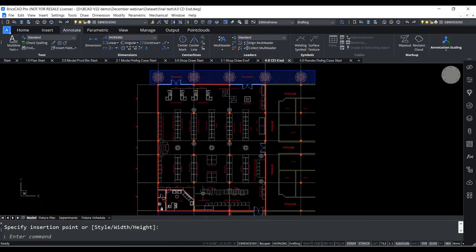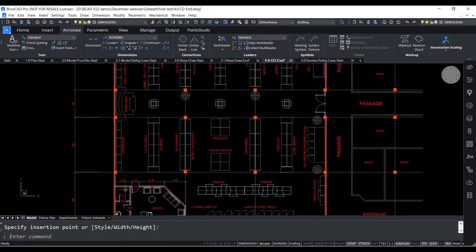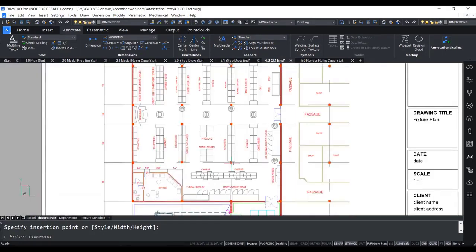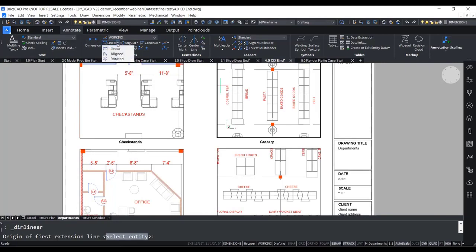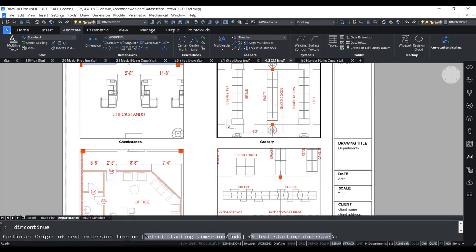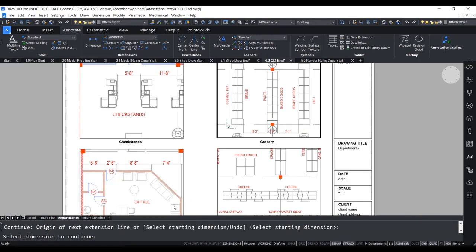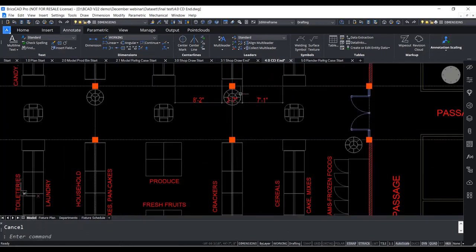What about construction docs for the 2D plan view of the store? Well, here we've got that. The dimensions were placed in model space. If you prefer, though, you can place dimensions through the paper space viewport. Again, a familiar workflow. Again, it's your choice. Also, notice the annotation and documentation tools are familiar. Well, what about your favorite existing dimension style? Well, if that's already in your drawing, then it's already available to use in BricsCAD. And of course, those dimensions display right here in model space.